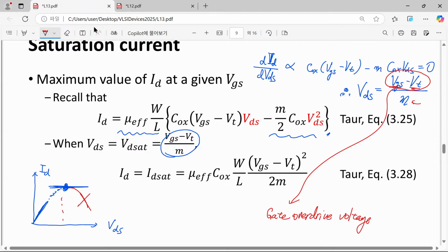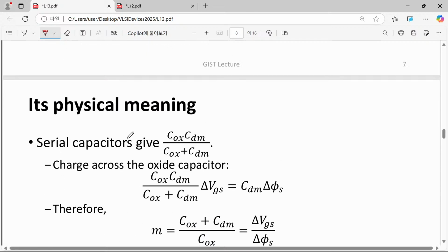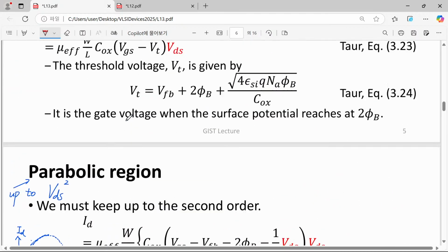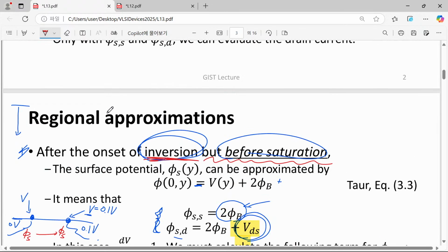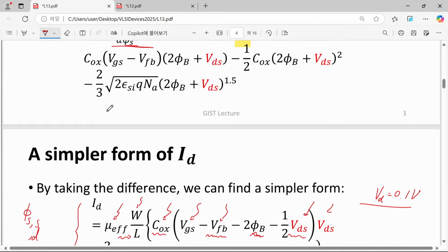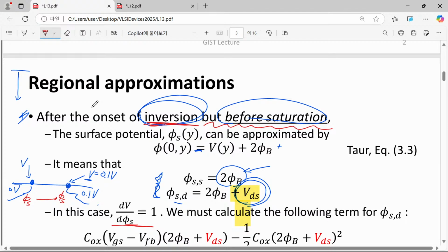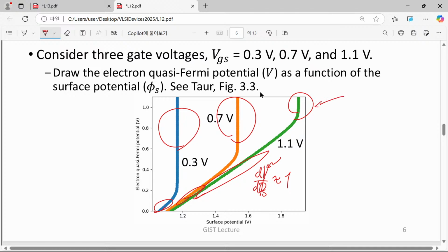It is obvious because this equation originated from our original approximations, and we have assumed these two conditions, that gate voltage is sufficiently high and drain voltage is sufficiently low, to prevent an operation condition like this one. This one should be avoided.